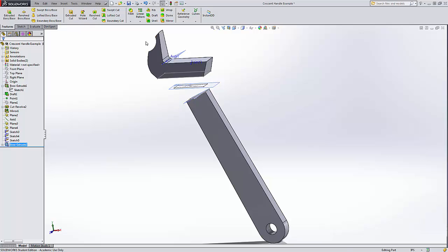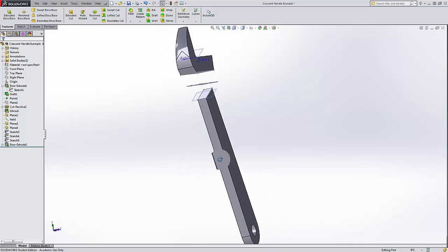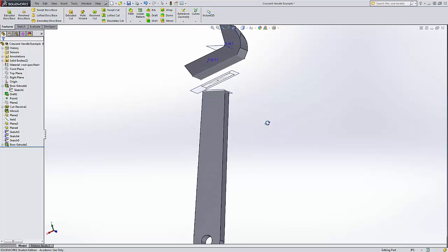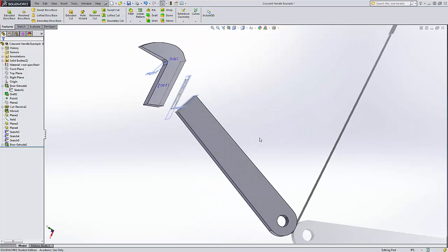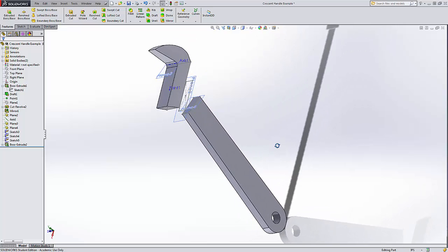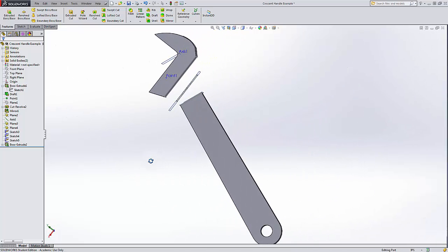And that's what we were hoping for. Now to make the cuts that go into this surface and this surface. The difficulty here was that I would like to use the shell command, but that does not do well when you choose two opposite sides. So it became just easier to make a cut of a certain depth and then mirror it.